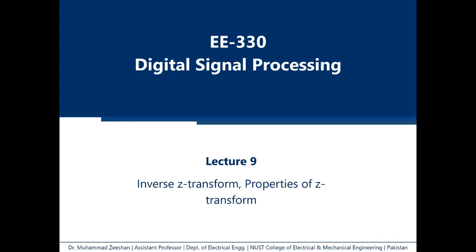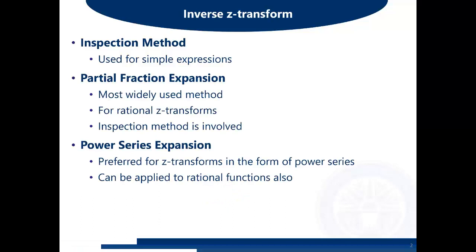Assalamu alaikum everyone. Today in this lecture of DSP we will be discussing how to take inverse Z transform along with several important properties of Z transform. So whenever we talk about inverse Z transform, it means we are going to convert the system function into impulse response, or any given Z transform expression into the time domain expression. So basically the conversion is from complex frequency, that is Z domain, into the time domain.